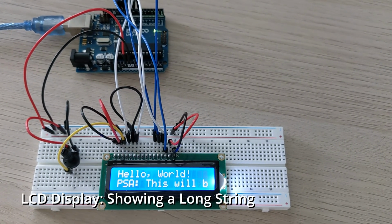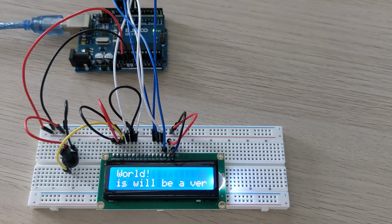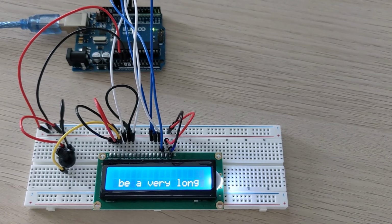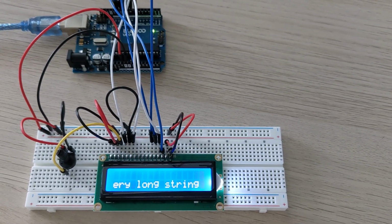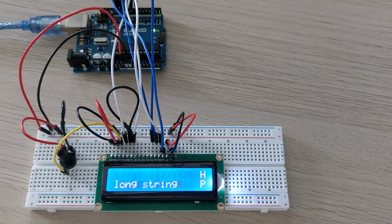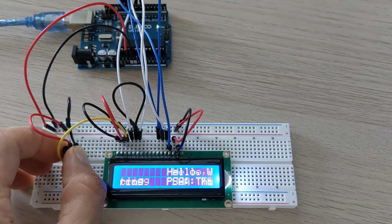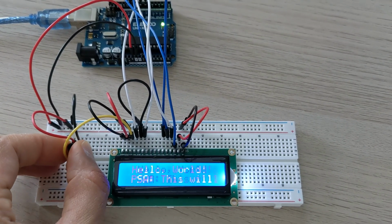Now we transition into the LCD display module. The scrolling effect is achieved by leveraging a functionality from the liquid crystal library. Here we are using a string of normal characters, but custom characters can also be used. In this case, the potentiometer is used as a signal of how bright we want the LCD display characters to be.